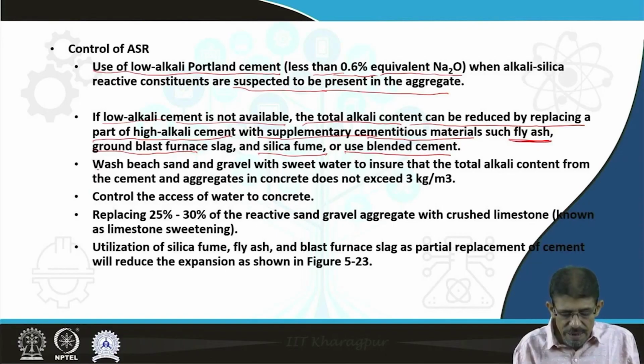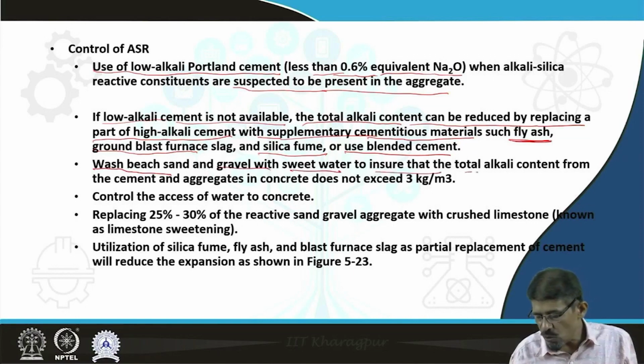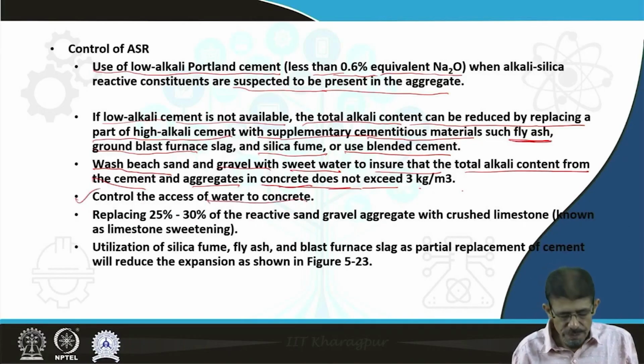Another thing, wash beach sand and gravel with sweet water to ensure that the total alkali content from the cement and aggregate can be reduced, and as per recommendation, the alkali in concrete should not exceed 3 kg per m3. Control of excess water is also helpful.